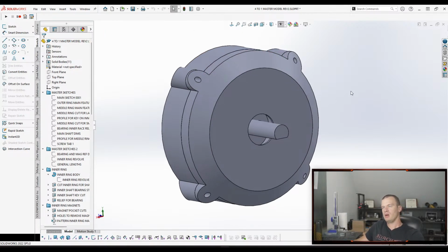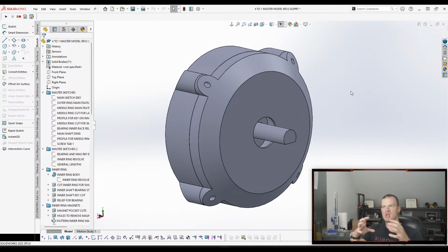So you're just sharing, and that's one of the key aspects of doing good skeleton sketches: you're only putting information in that sketch that is in relation to the two parts or multiple parts that you're designing off of it, right? So that's one of the advantages of doing the skeleton sketch.